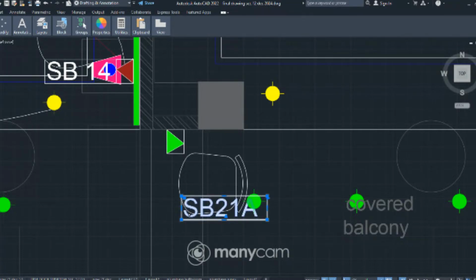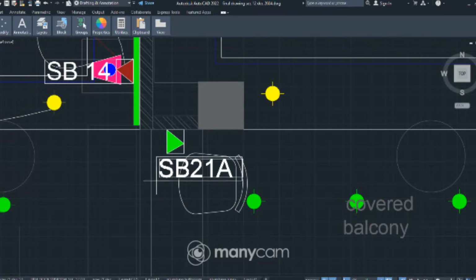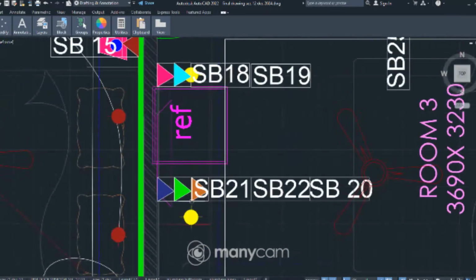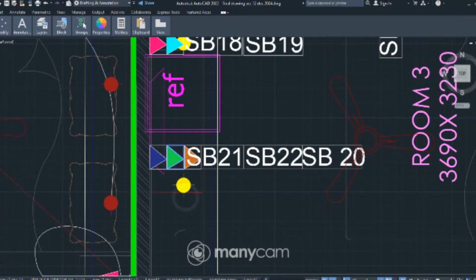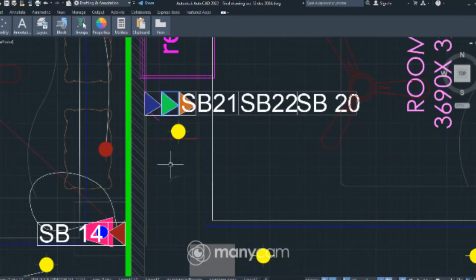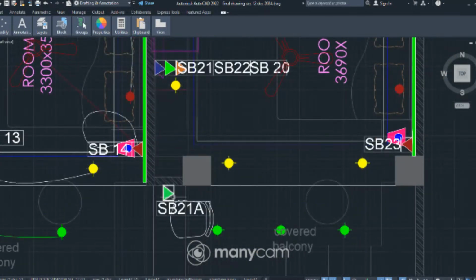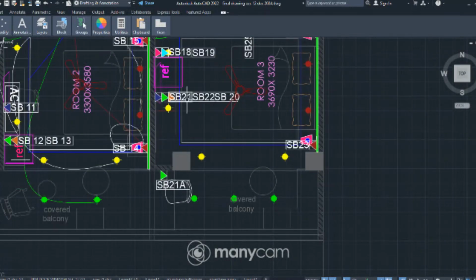So study table, we have to give one charging point for your laptop. So in this specific, we are dividing the plug points. So one 6 ampere plug point will come here in the chest of drawers to plug your water kettle, and one we are providing here for your charging.